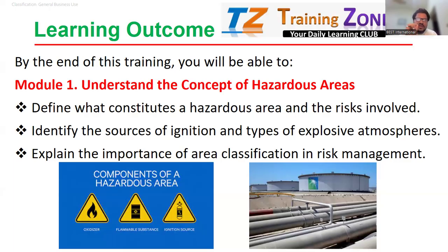So if that internal thickness is damaged, make sure we do a particular testing again and make sure we are taking preventions and putting some controls accordingly. And now the remaining is up to, if the fumes or substances or material are coming out and spreading up to 1.5 meter, this up to 1.5 meter we can claim is zone 1. But up to 6 meter, even up to 10 meter, we can claim it's all about zone 2. I hope you will remember that.